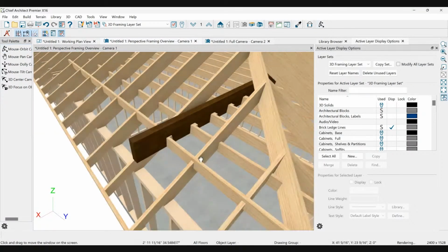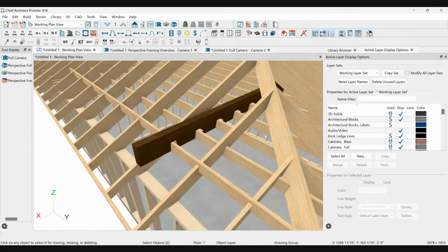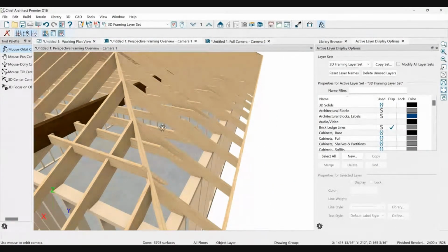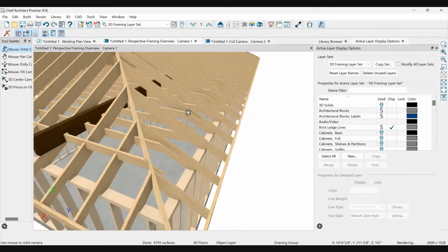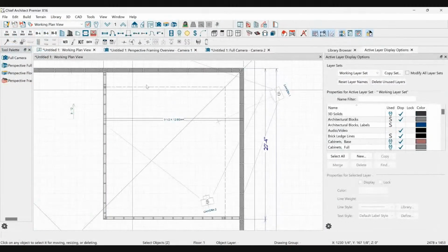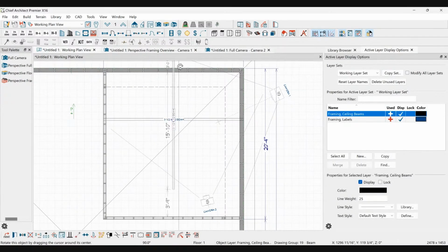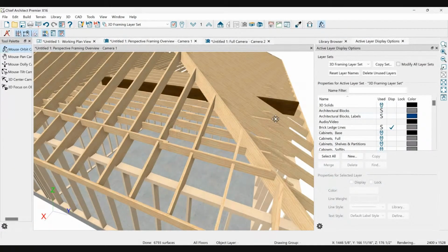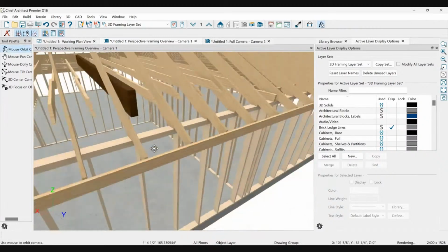Now, the reason it works with all the ceiling joists like this, this is typical. This works because each ceiling joist is light enough, it's not putting a bunch of load on each rafter. So it's not a big deal. But when you have a situation like this in the corner of a room, and you've done this to both sides, I can't put a beam either direction, right? Because if I run it the other direction, I have the same problem. So we don't see it in this view, but if I go this way, I have the same issue because I can't put it on the wall.